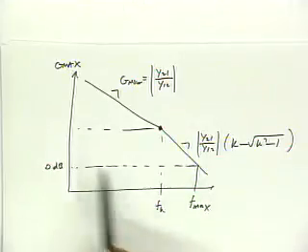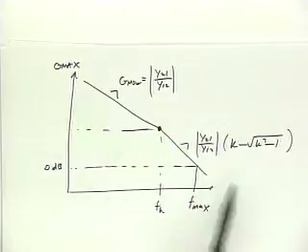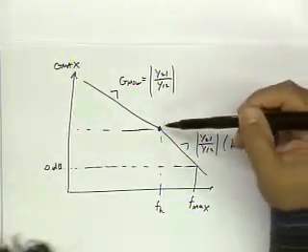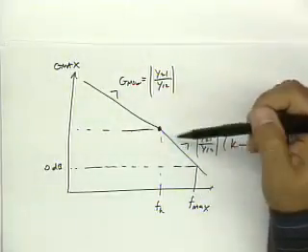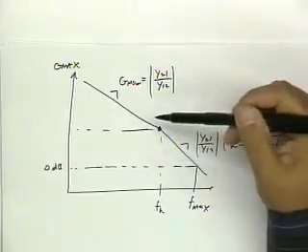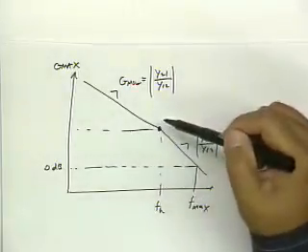So this is a very common way to characterize a transistor: you plot these various quantities, and this curve does represent the maximum gain you can get out of the device if you're just willing to change the source and load impedance. If I'm just willing to change the source and load impedance and to have a stable amplifier, this is the maximum gain I can possibly get.